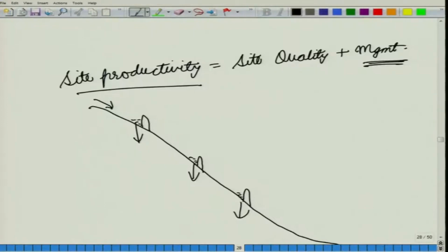At the same time, any amount of soil that was coming here with this water flow will also be accumulated here. So, essentially the amount of soil erosion will reduce. This is one kind of site treatment that we normally use in the case of forestry to increase the productivity of a site. In the place of bunds you could also go for contoured trenches.